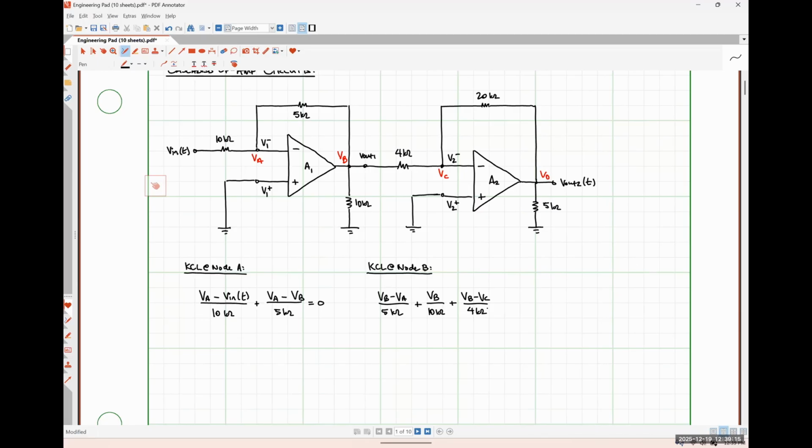So we know that no current goes into the terminals. Current flows out of an op amp. So this is exactly the trick I was trying to catch you on, okay? The ideal op-amp rules, and we have a negative feedback system, so we can apply the ideal op-amp rules, state that no current can flow into or out of the input terminals of an op-amp.